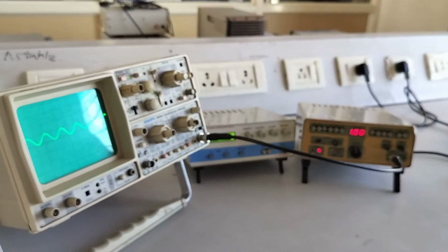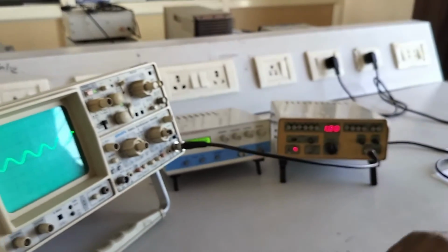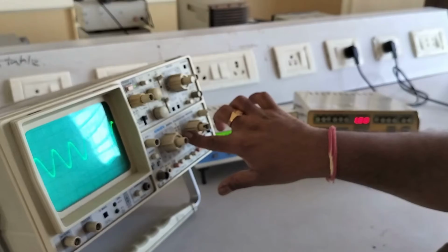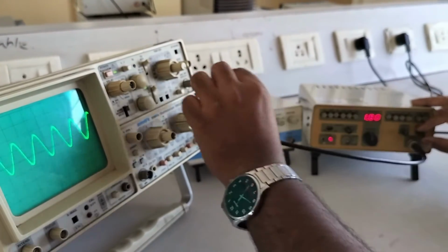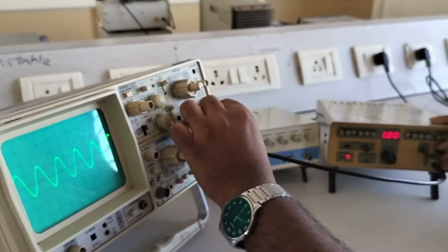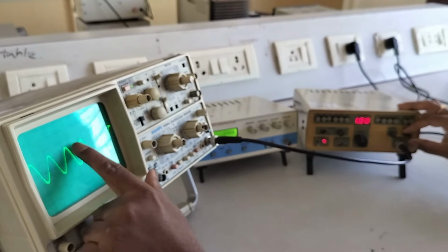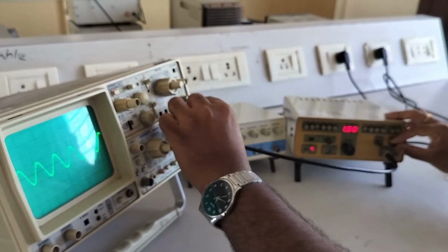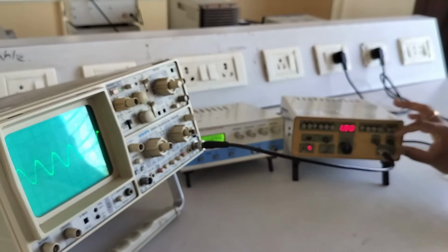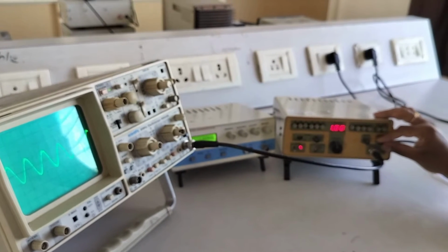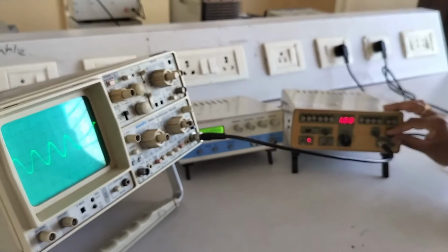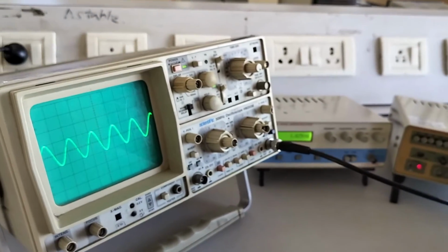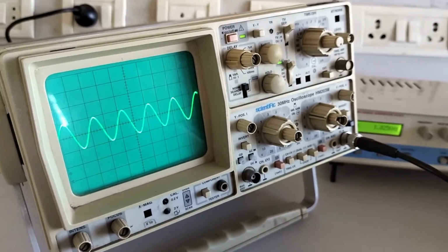Suppose someone asks you to adjust 4 volts. What you can do is shift it to the 2 volts per division position. Now I will adjust the voltage level in the vertical position to cover 2 divisions. I am adjusting the amplitude parallelly. See, it is the amplitude knob. I am adjusting the amplitude to 2 divisions. I will see that it is covered. So 2 into 2 becomes 4 volts. I have adjusted it. So this is how you have to adjust.